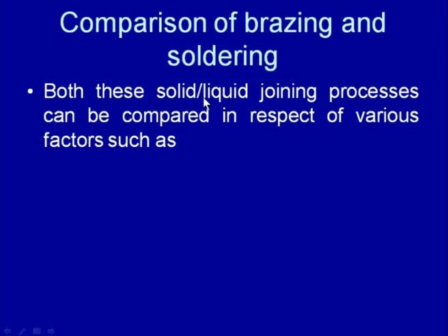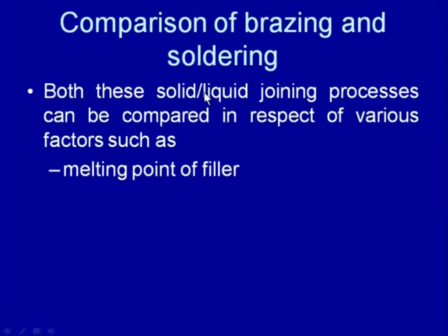Both these solid-liquid joining processes, brazing and soldering, can be compared with each other with respect to various factors. Brazing and soldering are different, but they have a lot of similarities in that both are solid-liquid joining processes, where the filler metal is brought to the molten state and the base material remains in the solid state. No melting of the faying surfaces of the base material is done.